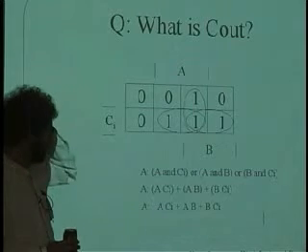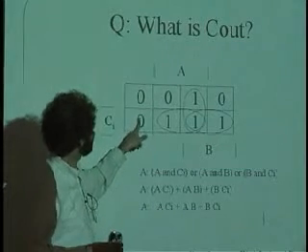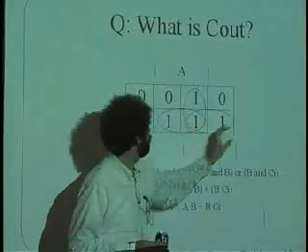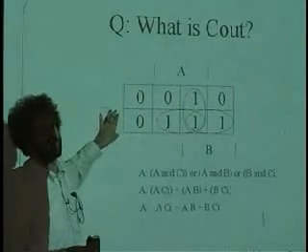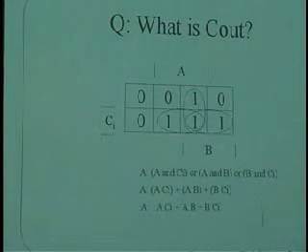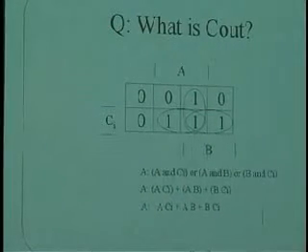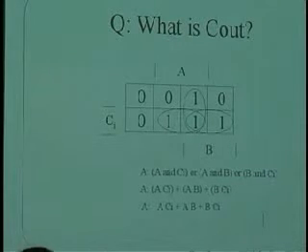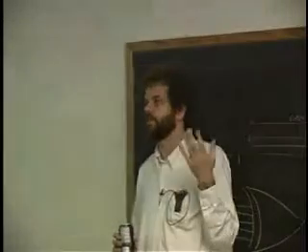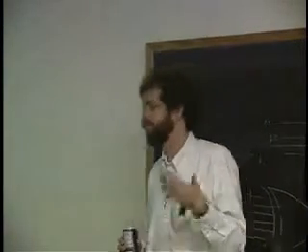Second rule you need to know is that, let's say that there was a 1 here and a 0 here, then you could have coalesced this one over here off to the right with this one over here off to the left. And again, you'll have practice doing that as well. And you only circle the ones of that? Well, there's actually 2 ways to do this, and in the recitation, I think you'll get practice doing it both ways. If you circle the ones, it has to do with the sum of products form, which is the OR of a bunch of ANDs. Guess what it is if you circle the zeros? Product of sums form. Okay, so you can do it the other way. Either way, you're just doing one of them. You're looking for groups. You are choosing one or the other, yes. You are not doing both.